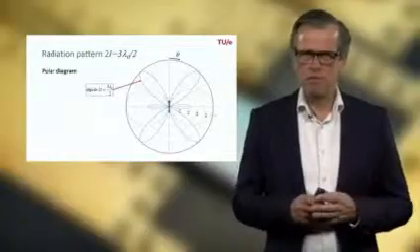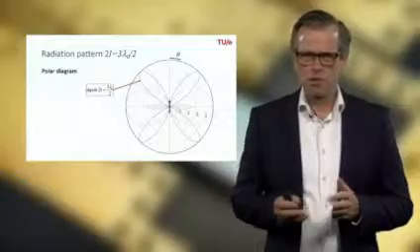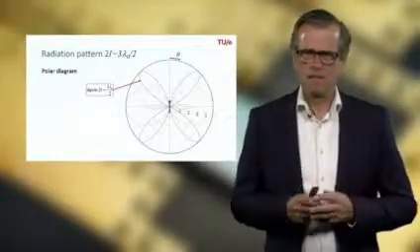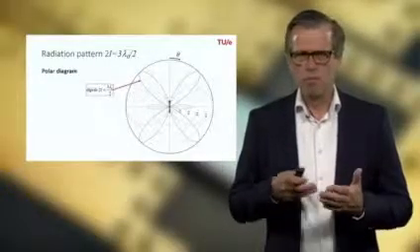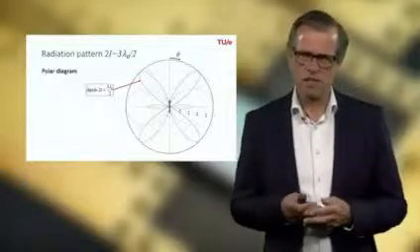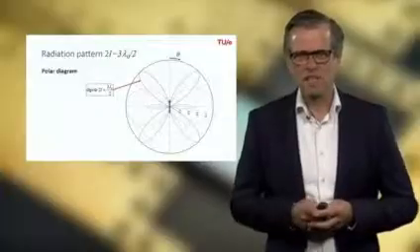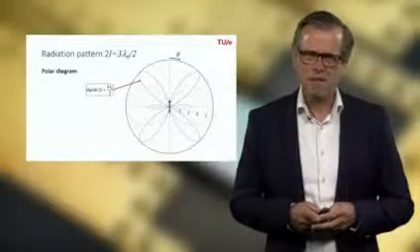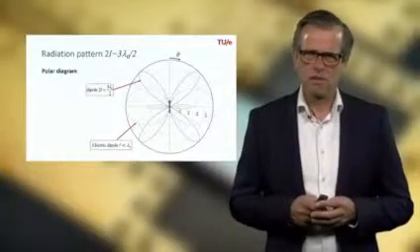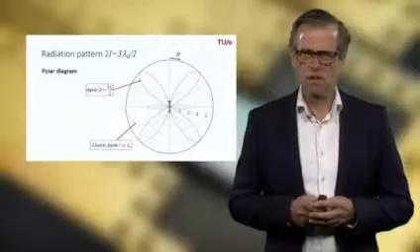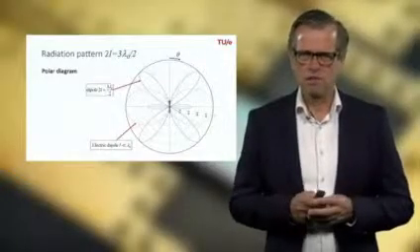And you might remember from a few slides before that we plotted the current distribution along the dipole, and if the dipole length is much larger than half a wavelength, you had multiple maxima of the current, so multiple harmonics, and that results also in multiple harmonics in the spatial domain, so in the radiation pattern, as you can see. So for comparison, the electric dipole is shown again. So this type of very long dipole is not very useful, at least not in most applications, because multiple maxima is usually not very beneficial.